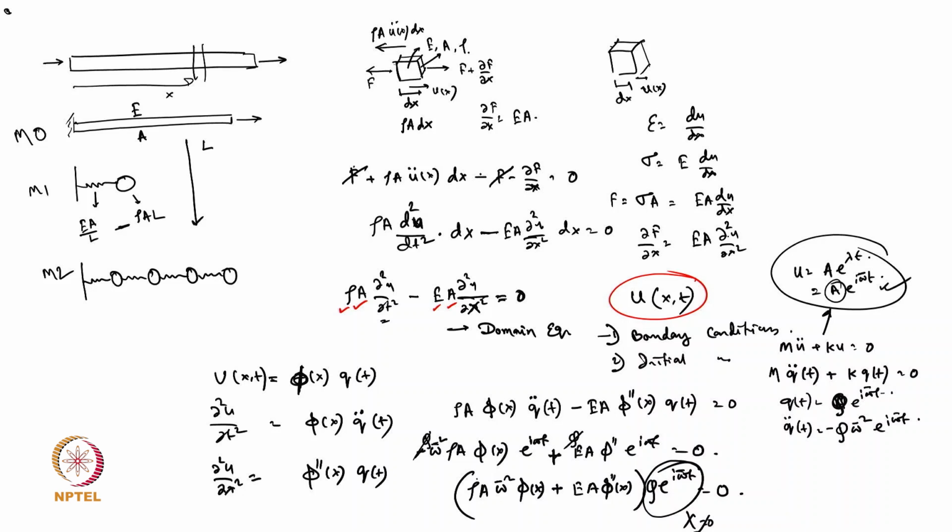So once we do the free vibration, all infinite number of modes will come into picture, and we have to do the summation of all that. Because in case of a multi-degree freedom system, we have seen that we have to consider all the modes. So the free vibration problem becomes more difficult in case of multi-degree freedom, because all the modes' contributions start coming into picture, which you cannot neglect.